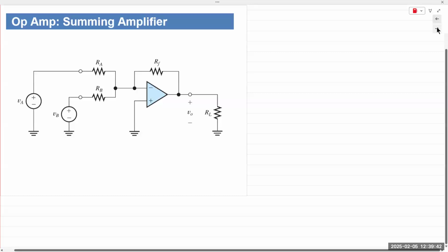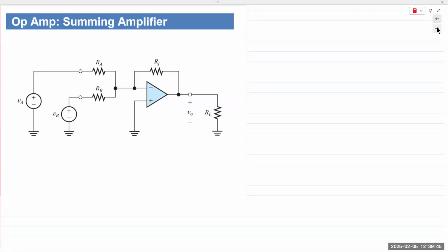So if we add one more resistor to the inverting terminal, we can apply 2 inputs. If we add one more, then we can apply 3 inputs, and so on and so forth. And thus, we obtain something known as a summing amplifier. So this performs the operation of addition. Okay, summing amplifier performs the mathematical operation of addition. By its very definition, it is a differential amplifier. It amplifies the difference between any two signals. This is a summation of 2 or more signals.